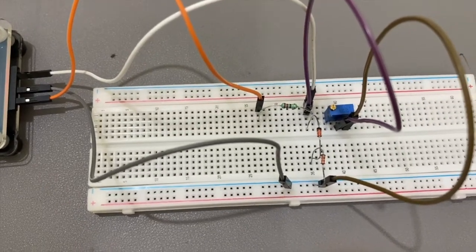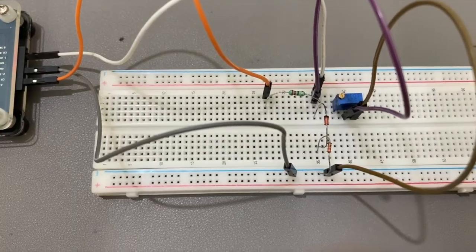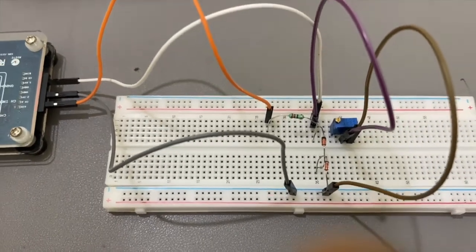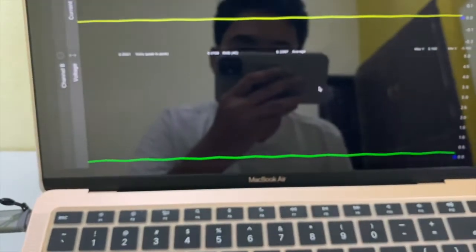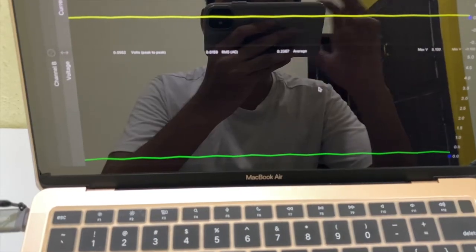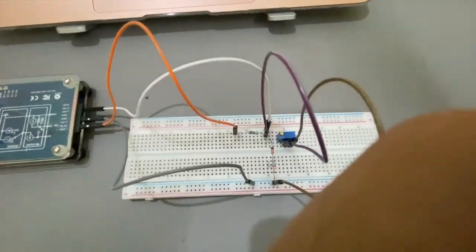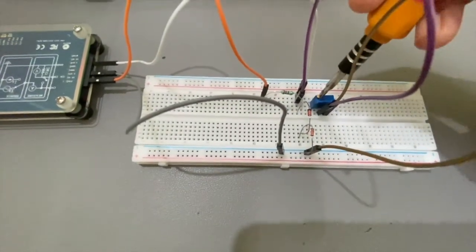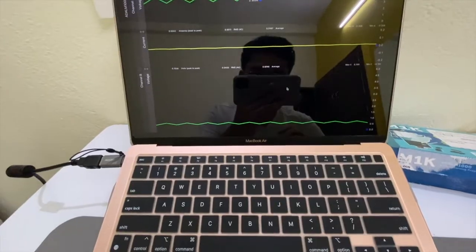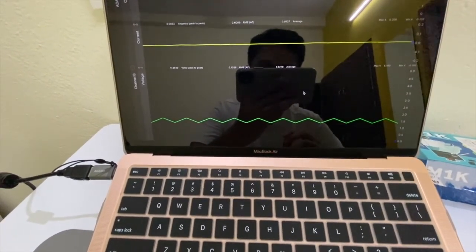So to conduct current in the reverse bias condition, the output voltage of the load resistor should be greater than 7.2 volt, and then the Zener diodes start conducting current in the reverse bias condition. As we see on the screen, currently the output of the load resistor is approximately 0 volt. When I increase the value of the load resistor, my output voltage will increase. It will increase till it reaches the breakdown voltage. After that, only the current of the Zener diode will increase.